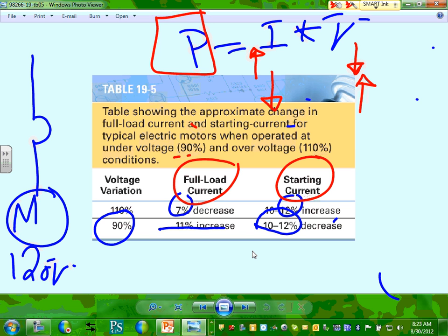But the starting current is typically 6 times the full load current, right? So just for 10 seconds, the equipment will draw 6 times more current than it normally does, to try to push that beast to start, depending on windings, a bunch of other things, and the design of the motor. After 10 seconds, the current goes down to the full load current. Any questions, guys? Any comments?